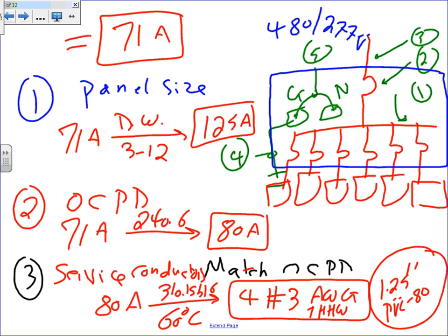Everybody knows the difference between a feeder and a service entrance conductor. The first conductor comes to the building, lands on the panel, it becomes a service panel. This is assuming a service panel. Now, if this wasn't a service panel, if it was a sub panel somewhere downstream, an equipment panel, nothing will change. The only things that will change are two things. There is no main bonding jumper, it disappears, and the grounding electrode conductor becomes the equipment grounding conductor, and it's sized from a different table. It's the only difference. The calculation continues to be the same.